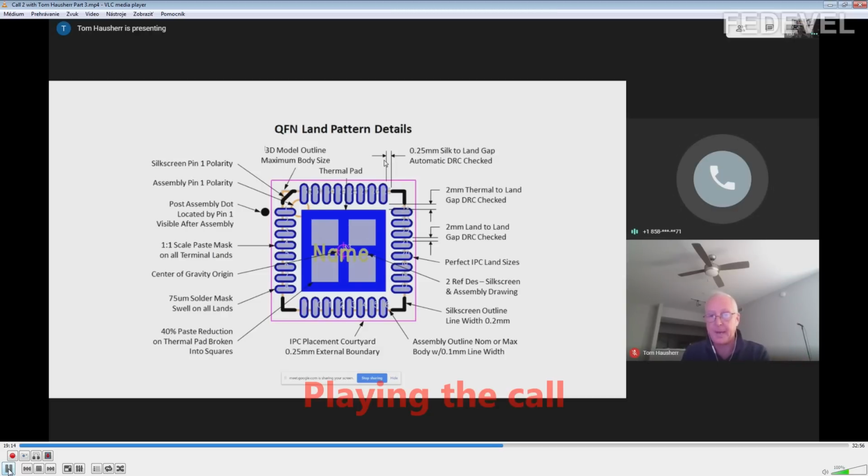Are they using rules like minimum pad to pad rules, minimum silk screen to pad rules, okay? So all these rules that we're talking about here are in library expert preferences. I said we have 1,000 preferences, and the user can go into the preferences and just change all the preferences that they want: the silk screen legend line width, the legend line gap, the assembly line width, what kind of polarity you want. You could assign all these preferences, and then when you go to put in the package dimensions, it auto-generates a pattern per your preferences.